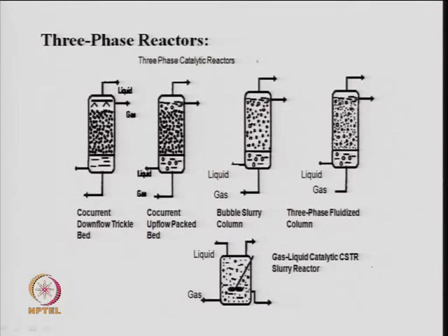Here you can see that you have a solid inside the reactor, a bed, and then the flow can be co-current or counter current. That also depends on the concentration difference which is required, or the kind of contact between gas, liquid and solid which is desired. So, both types of combinations may be used. Here you can see the liquid comes from the top. So, we need a distributor here.